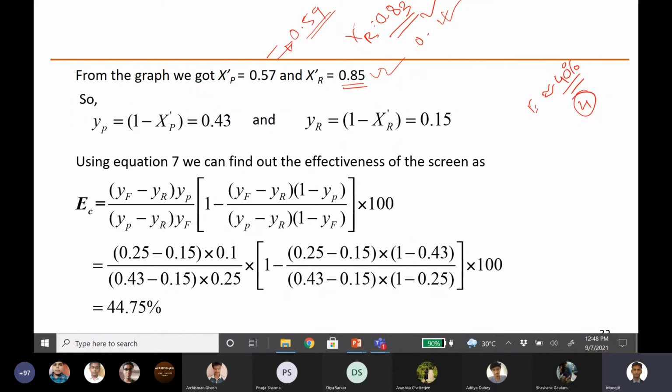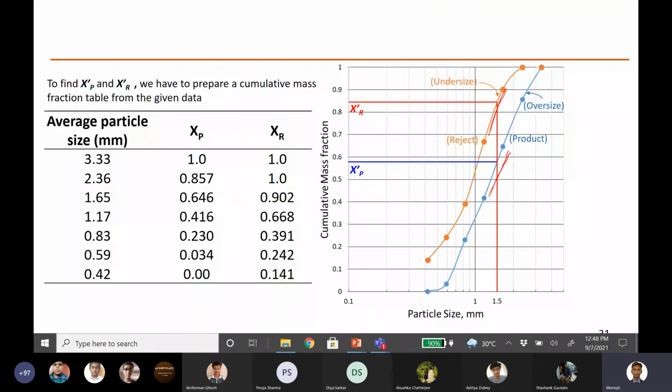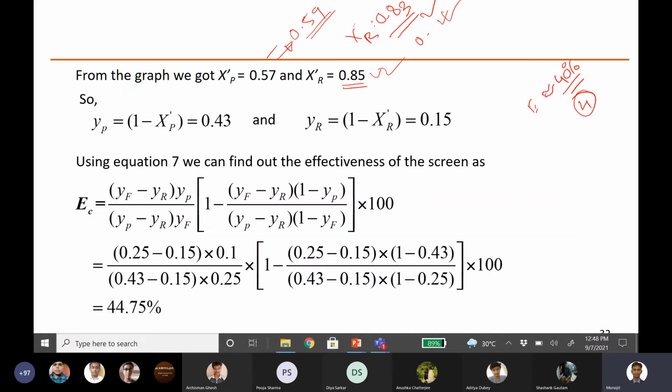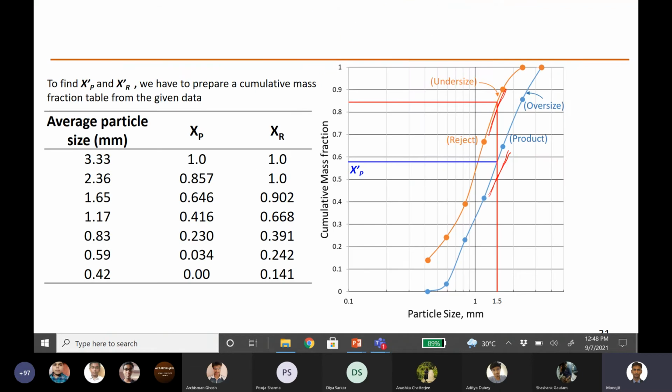See, this error may reduce depending on your distribution. If both fall into a linear regime, then you might get relatively less error compared to the actual one. But the actual one you will always get using a graph. So that's why we always go for a graph without using linear interpolation. And a graph can also give you error if the data points are very far apart.